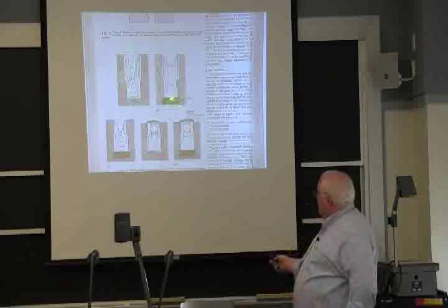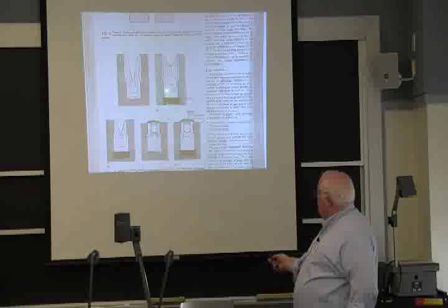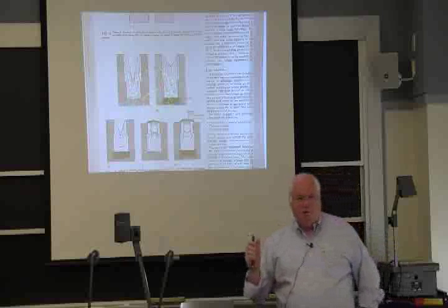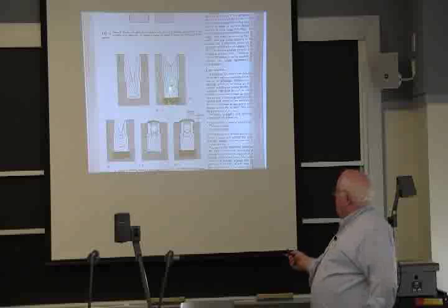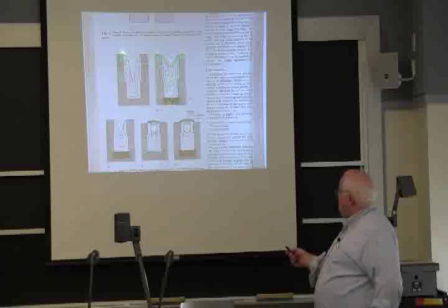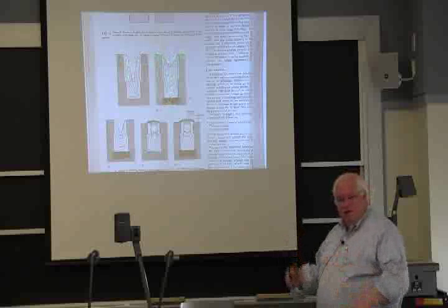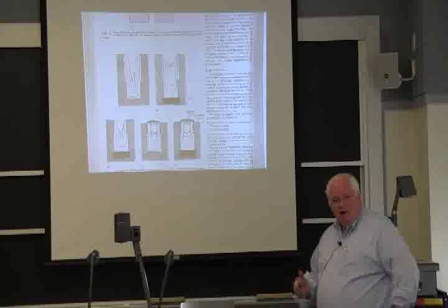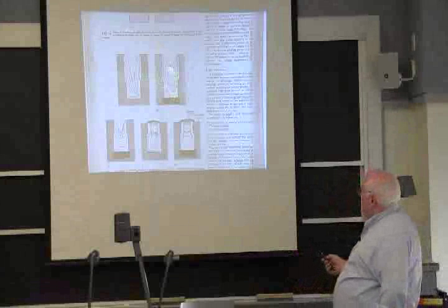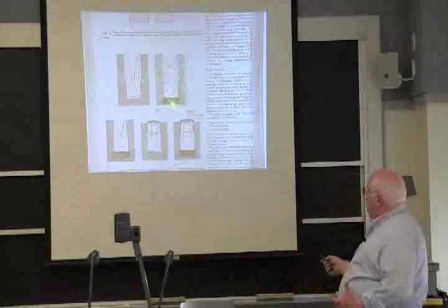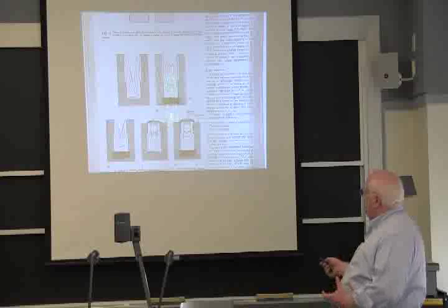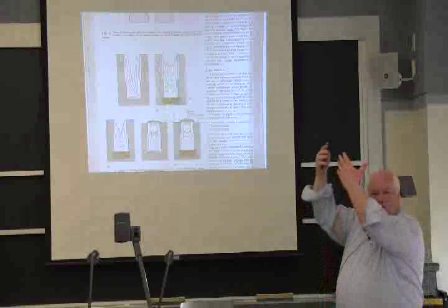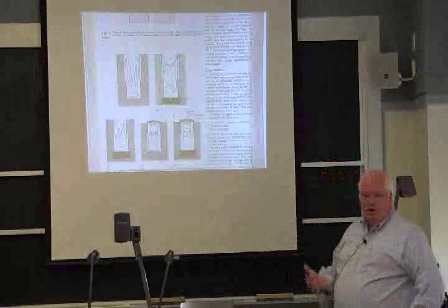If you do some other things like put a chill block in here so that you extract a lot more of your heat from the bottom, you actually can get rid of a lot of that pipe. And so you're starting to shrink here, and so a lot of the volume here is the same as the volume of that. Remember, you got this radius thing you got to worry about. So the volume out here at a large radius is much greater than the volume of that area there. It's r dA, if you will. In any case, if you were to cool entirely from the bottom, all you're going to do is push all your shrinkage up to the top, and you'll have a very flat surface across here if you think about it.